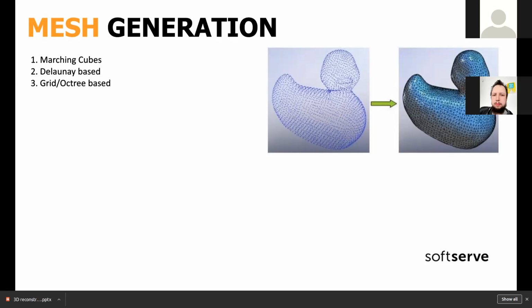But with that, this method also has some constraints regarding the material of the object. It's not suitable for dark objects or objects that are glittering, and also objects with hair or fur. But otherwise, after calibration and fixing the setup, this method is quite robust and has a very good resolution.